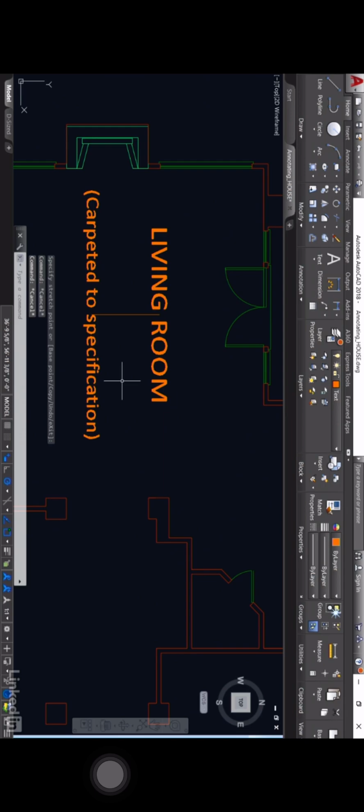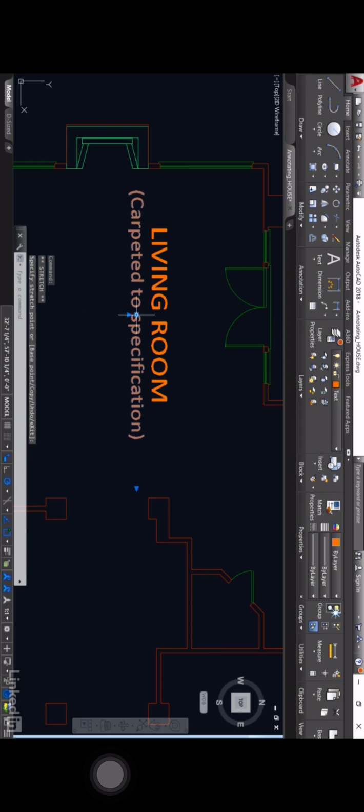I now know that those two middle center justifications line up. I delete the line, and now all I've got to do is click here, click on the grip and just move that vertically up using my polar tracking, click there and hit escape to deselect, and it's all nice and neatly centered. So that's how you add and modify your text, both single line text and multi-line text, in an AutoCAD drawing.